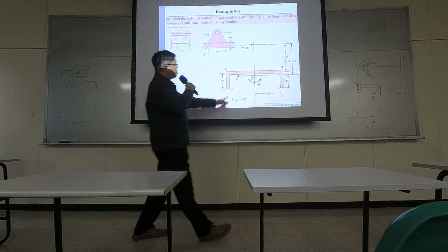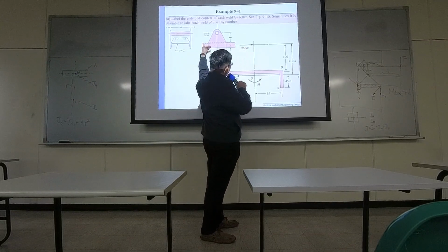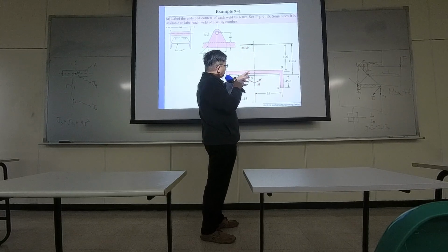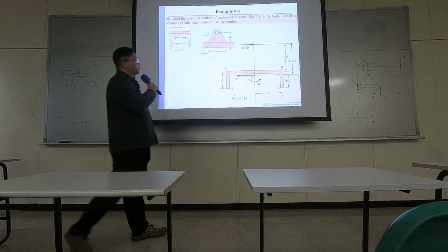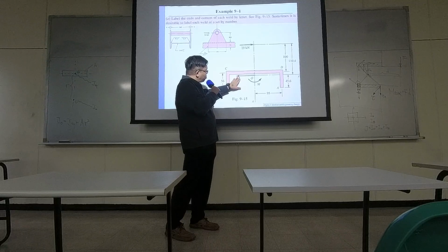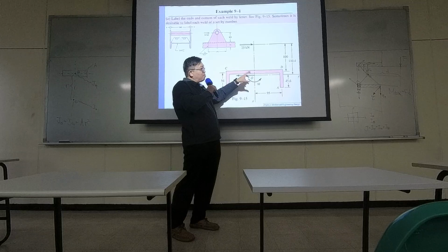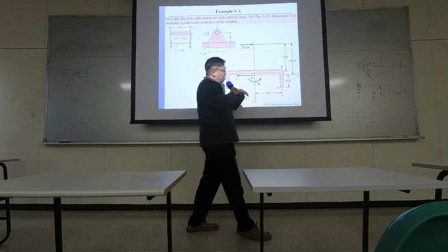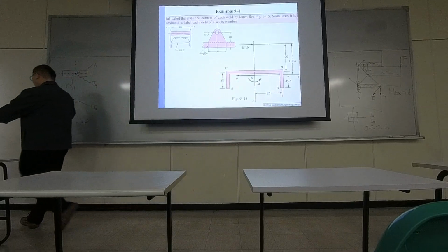This reactive shearing balances out this external force going right, and this reactive moment balances out the external moment caused by this external force going right. And this reactive shearing, normal shear, and the rotational shear due to the moment will be distributed into all the welding materials.